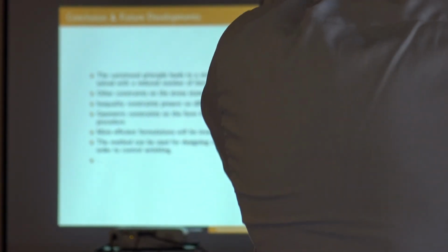No, the static configuration, anything can be a straight line. So this is like the starting point of the Newton process. You start with something, and the length constraint is imposed variationally. It's not enforced from the beginning. So you could start with anything. Yes, usually we start with a line. That's the idea. It's not to be too far, of course, but it's just the radius of convergence of Newton. Then one of the conditions is the one that forces the length.